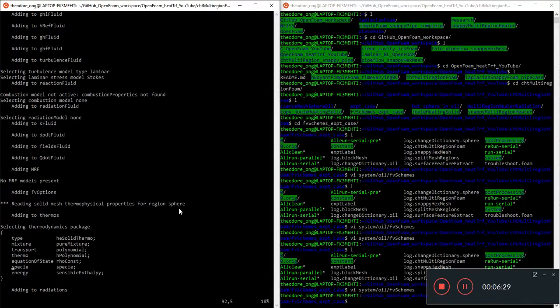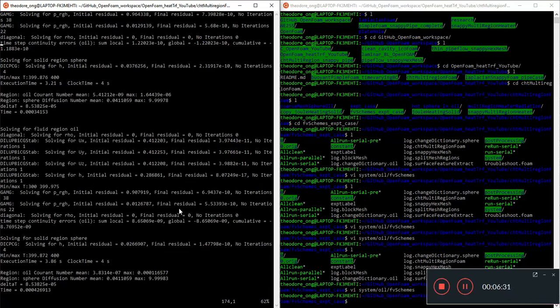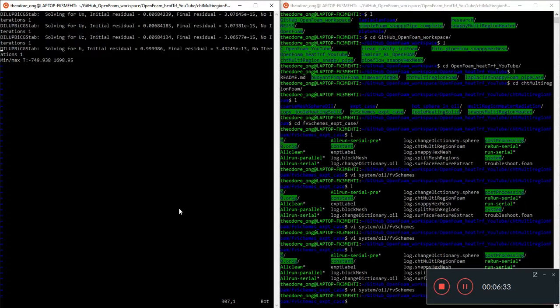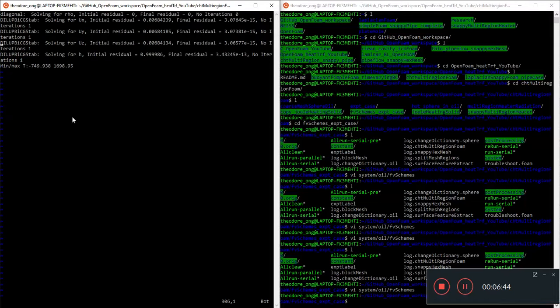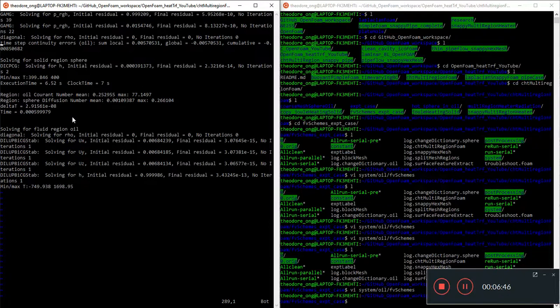There were several steps I went through, but after several iterations, you see the temperature actually jumping to about -700, which is non-physical, and of course the max temperature is 1700 Kelvin. Again, this is not a physical result. So there's obviously something going pretty wrong with this situation.